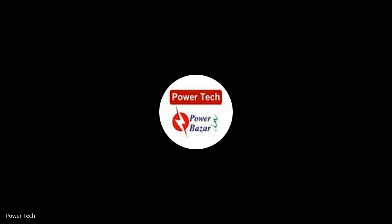Poonam Dogra ji has asked, are any penalties being imposed for harmonics in any state? Yes, Tamil Nadu started long back. They had a penalty on harmonics, and it was 15%. Suppose your harmonics are not as per IEEE 519, you will be charged 15% of the power bill. And now Maharashtra has started, but they are around 7% or something.